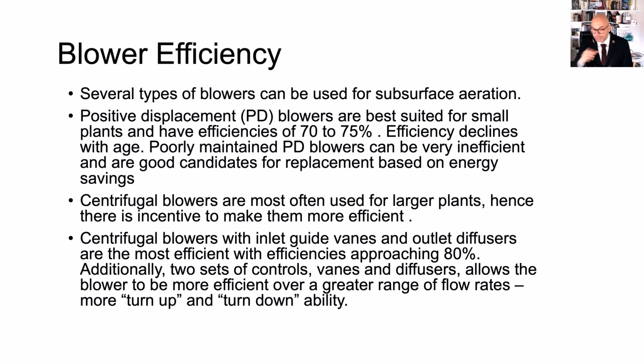So blowers that are centrifugal in nature have a propensity to go to surge if there is too much pressure, but they can also be very large. So large plants always use centrifugal blowers. And for blowers that need to be used with variable pressure, but not with a big difference in airflow rate, as in plants like sequencing batch reactors, perhaps MBRs, then positive displacement blowers become a much more appealing type of technology.